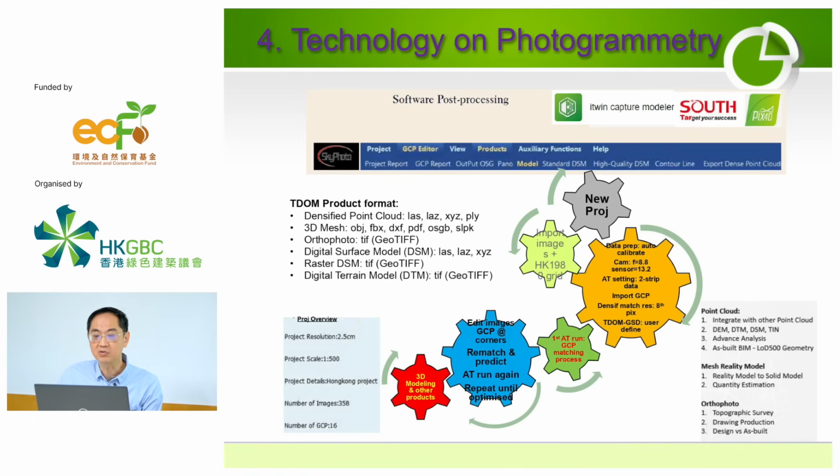We input our ground control points if we only have the photo information. The photo information, in fact, has its metadata about the lat-long, the position, but it is not quite accurate, you know. And then we need to give them some ground control points so that the software can adjust to make the flat surface flat, okay? The curved surface curved, okay?